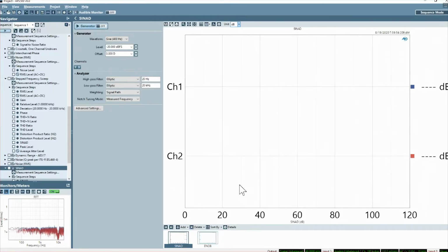So in particular, the delta sigma modulator we implement inside of APX for the PDM module, it only accepts, my memory is not quite perfect on this, but I believe it's some dB less than full scale is the maximum signal it will generate. So that's an issue. But I think to the core question, it's still a digital to analog or analog to digital converter, and these measurements remain relevant.